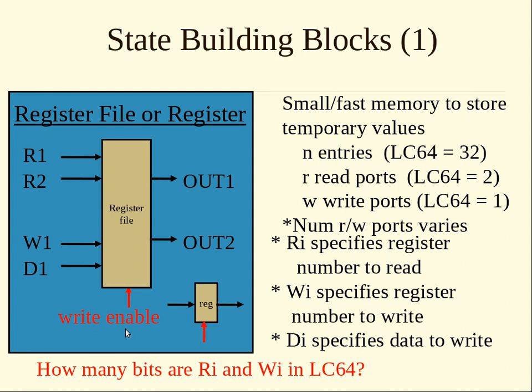And then we have a write enable bit, which is basically used to tell the register file if it's actually writing something or not, because some instructions aren't going to write to the register file, so we want to make sure that we don't accidentally write to it. And I probably should have gone over this first. A register, in this case 64 bits, does have a write enable line of whether you wish to update the register or not at some point.